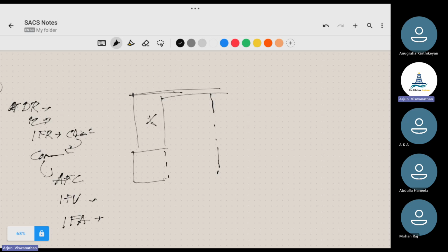The ports will be very calm because they have breakwaters. Breakwaters are just a wall of rocks. We keep them so that when the waves come toward the port, they will not get inside. So the water will be very calm. When we lift in the port, we can select a factor of 1.1.